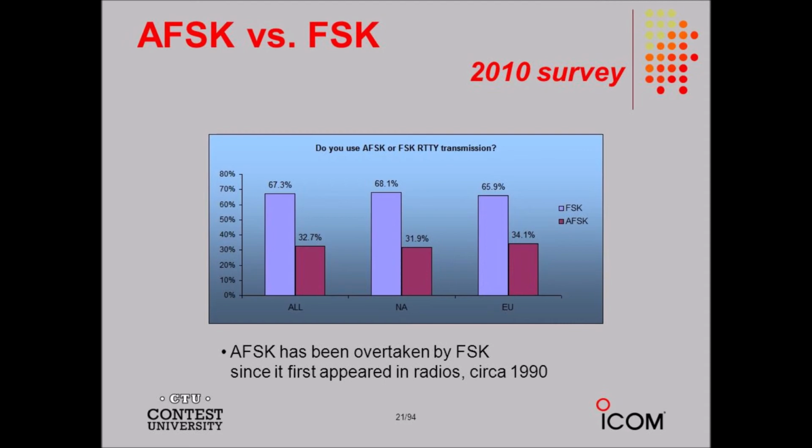The varying voltage across the varactor causes its capacitance to change in accordance with the audio waveform. The fluctuating capacitance causes variations of the resonant frequency of the inductance-capacitance LC-tuned circuit, causing small fluctuations in the frequency generated by the oscillator.